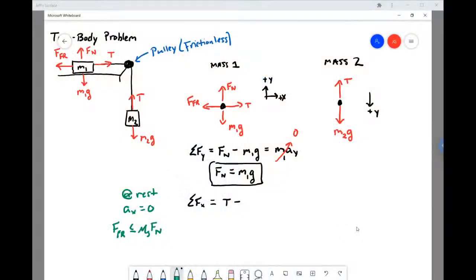So we'll set up the problem using the maximum value of static friction in this expression, and then we'll figure out what M2 will be when that maximum static friction is attained. And then if M2 is any more, you drop a feather on top of M2, everything starts sliding. All right, so we will say here then that the frictional force is equal to its max.